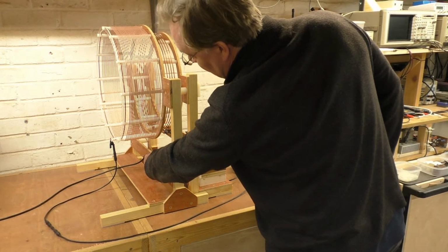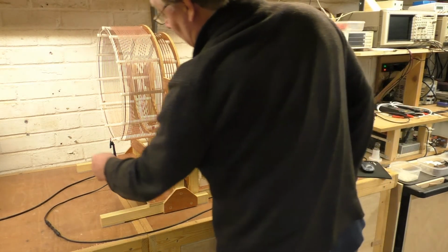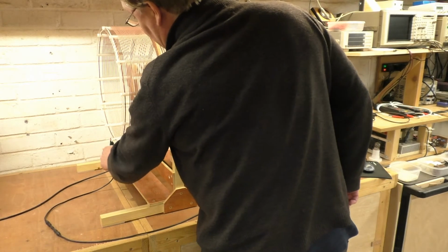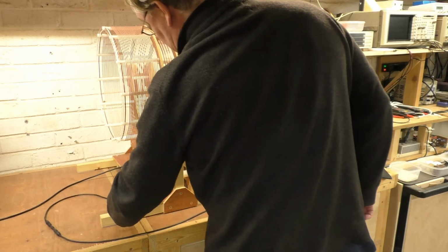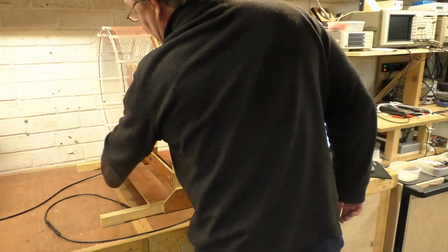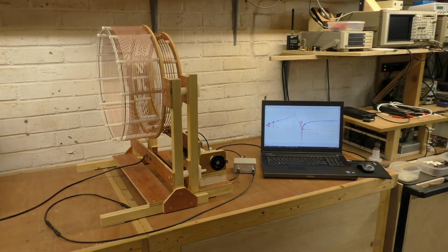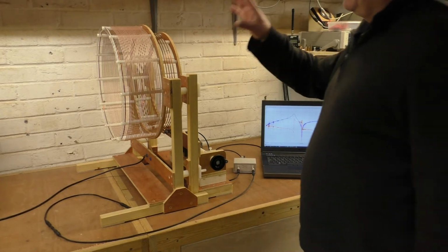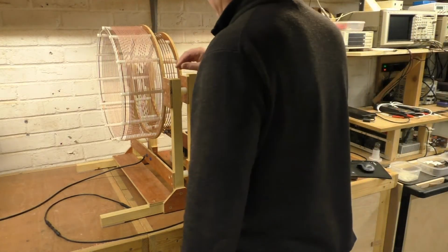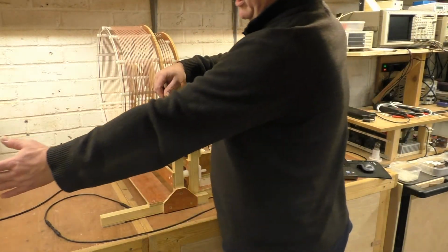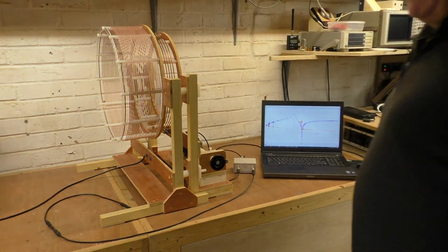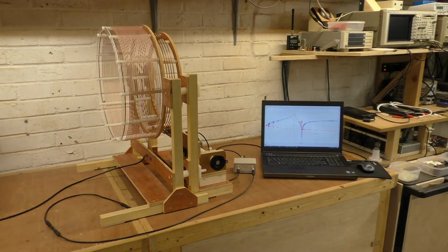This is the output, the low end of the secondary coil. This is the high end of the secondary coil. If we just take that off for a moment, and we have a length of wire at the bottom end reducing the impedance there, that puts it in a quarter wave mode. I can also connect that down to a dedicated RF earth, and on the other side I also have a dedicated RF earth at the other end of this wire, which I can connect that to.